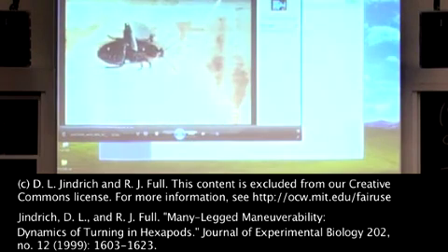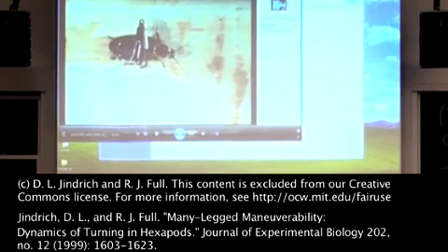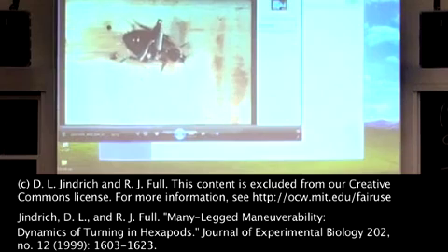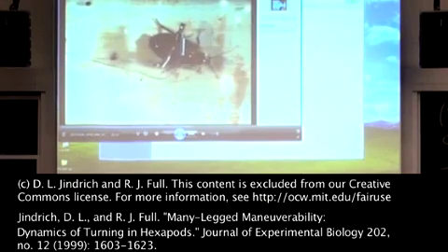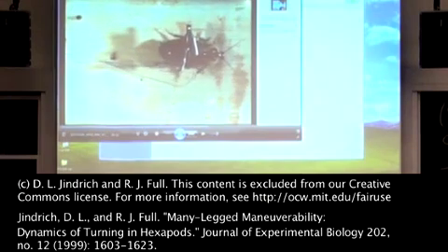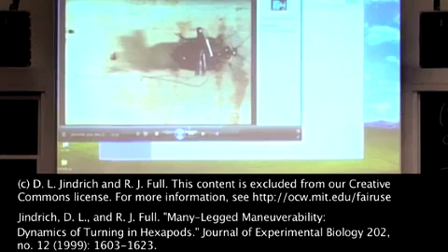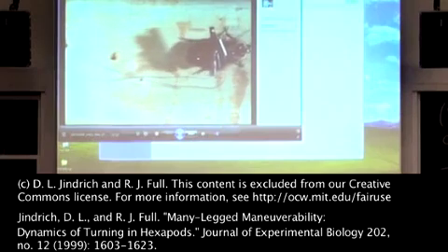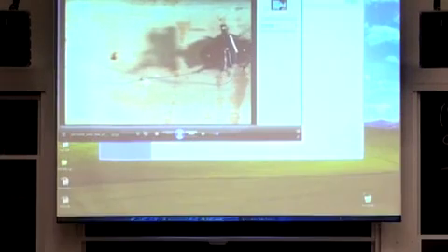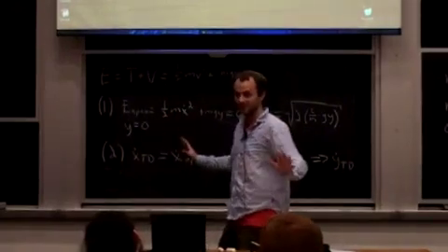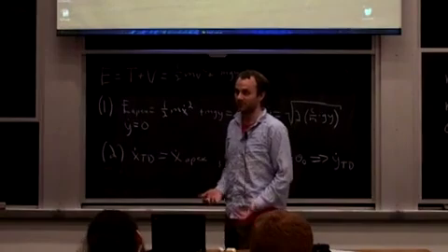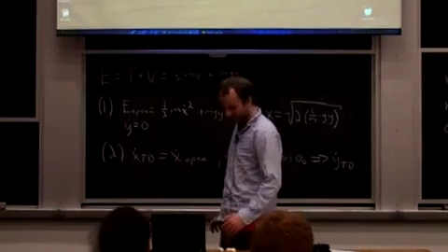But you see, that's just a fantastic little experiment. And the perturbation, as you see, it doesn't know that's coming. That hits it like that, and it just responds almost instantaneously. So I think that's really cool. And that shows that's SLIP in the lateral plane. It shows that these springs and this compliance in the animal can actually do things that control just couldn't do. The time scale of the response can be faster than control could achieve.